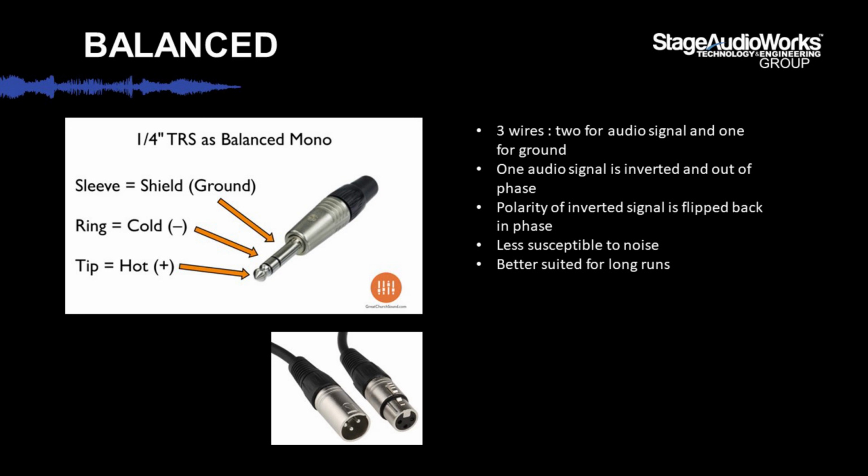You could use this insert cable if your device is, let's say, a home theater CD player or something, and it has a big 6 3/4 inch jack on the front of it. You could use this cable to break out from the headphone jack, which is stereo, into 2 unbalanced monos. It's important to know that just because it has 2 black rings, it doesn't mean it's stereo. Most of the time, at least in professional audio, it's not stereo, it's actually balanced.